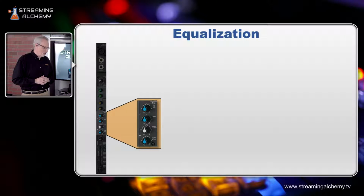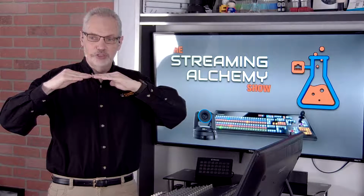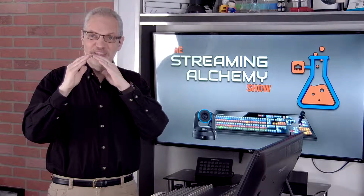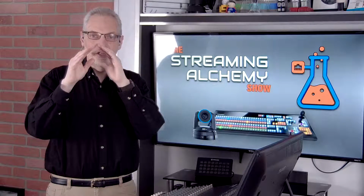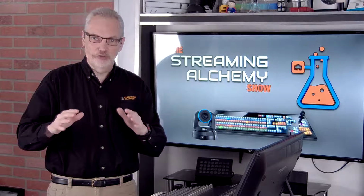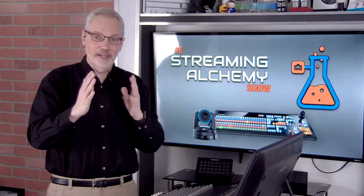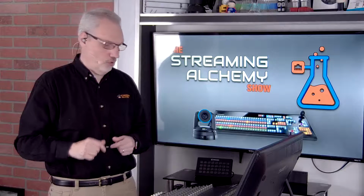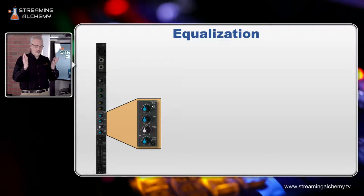So what you end up with, as opposed to adjusting that one frequency, which could be sitting here, is that as you adjust that, frequencies that are within that space of what's called the Q are also going to be adjusted, but in a nice curve. So it's more of a bell curve where you can control how wide I want that frequency adjustment to be. And it gives you now a range of control. In this case, the low and the high, that's built in. There is a fixed Q, which is usually somewhere around a 1 octave range, frequencies up and down.